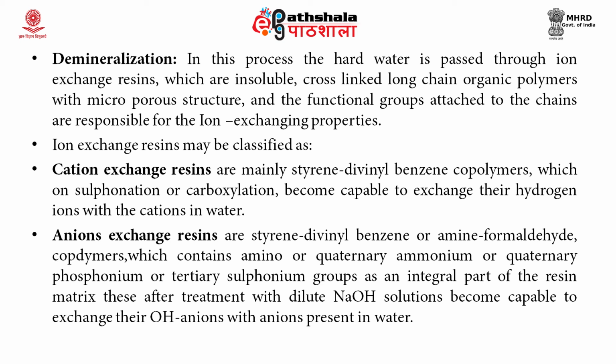The anion exchange resins are styrene-divinylbenzene copolymers which contain amino, quaternary ammonium, quaternary phosphonium or tertiary sulfonium groups as an integral part of the resin matrix, and after treatment with dilute sodium hydroxide solution they become capable of exchanging their hydroxyl ions with the anions present in the hard water.